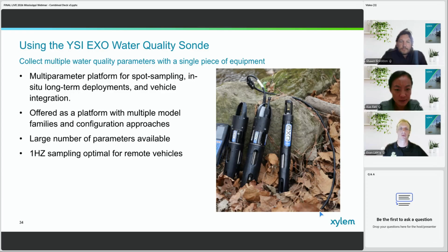Okay, yeah. On the Seeker models and the Duet, the max speed is 4 meters a second, which is quite fast, and that's some really quick water. The fastest autonomous transect I've seen done is at 3.5 meters a second in New Zealand. They weren't driving it, so with a little bit of speed overhead, the fastest flow would be approaching 4 meters a second.